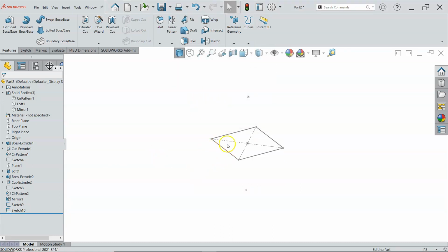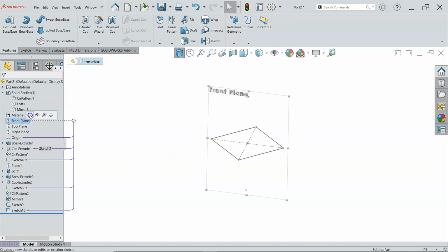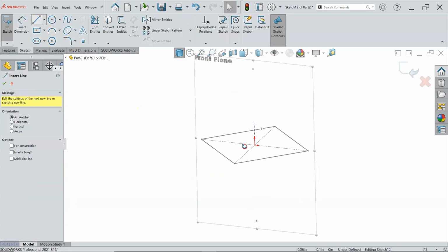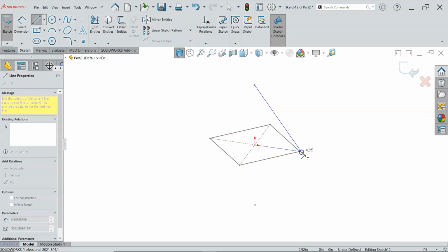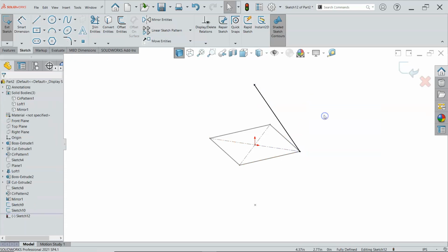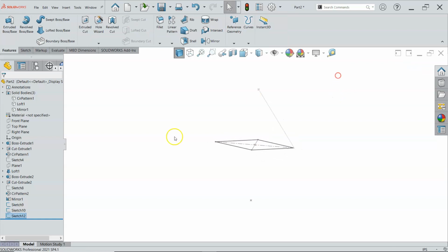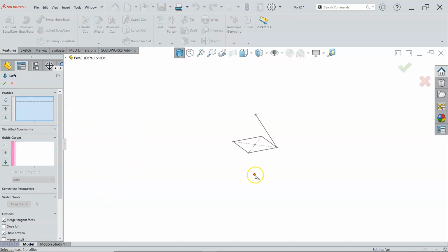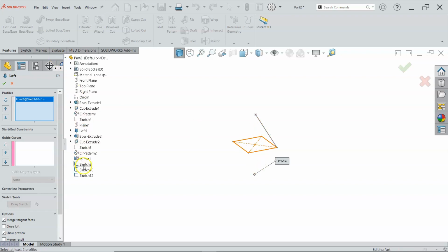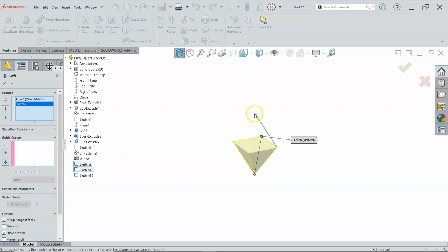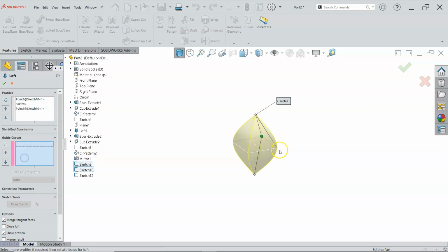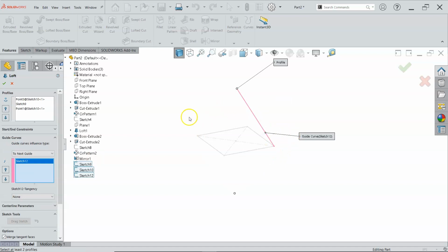And what I'm looking for is to create a guide curve in the front plane that will force those to stay more linear than trying to curve through the lofted geometry. All right, so that gives me a guide curve. So if I go back into the loft, and making this way more complicated than it probably needs to be, pick our geometries, and there is sketch 9, and we'll bring it up to sketch 10, and then what the guide curve should do is cause an error.